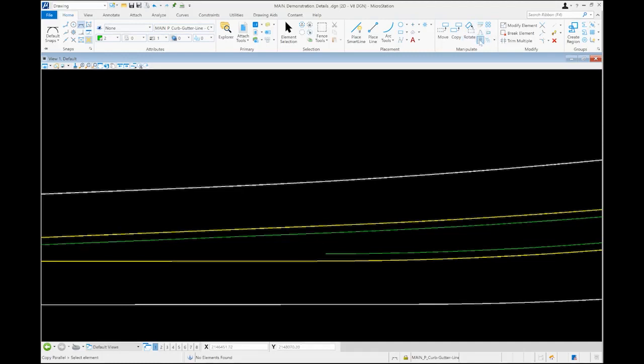So within that typical range of 2 to 4 feet, we're going to split the difference and use a 3-foot offset for this particular location. And I'm just going to set an offset line there as a point of reference. And then we're going to use a 2-foot radius for this approach nose. Again, splitting the range, typical range of 1.5 to 3 feet. We're going to use a 2-foot nose here. And then what we'll end up doing is deleting this construction line and then inserting a transition in between our nose and our typical 2-foot offset.